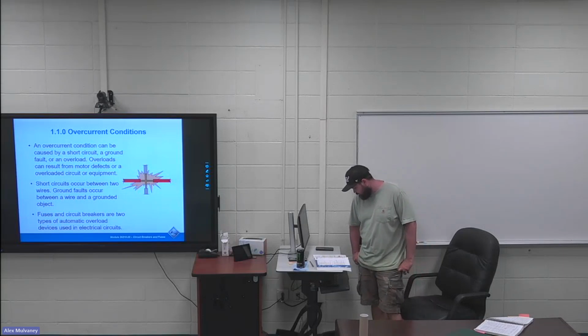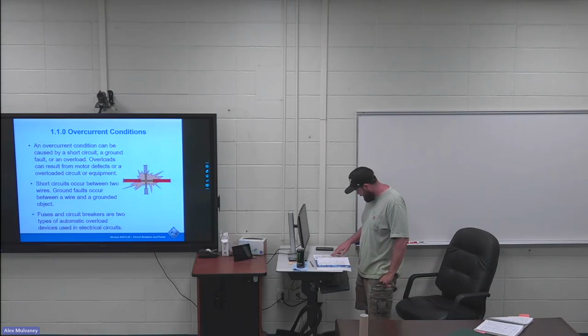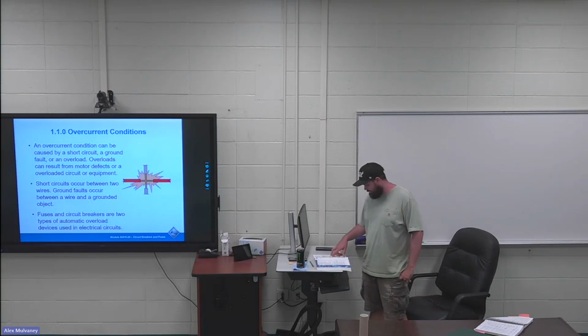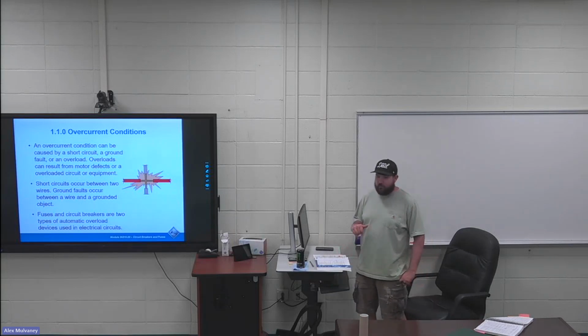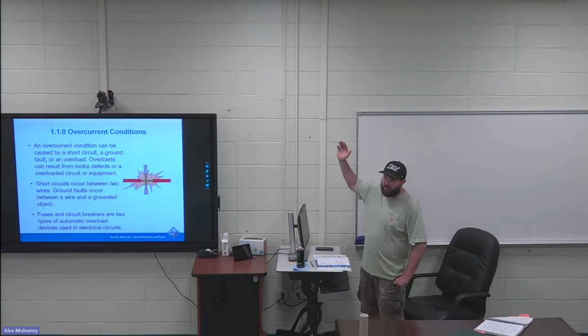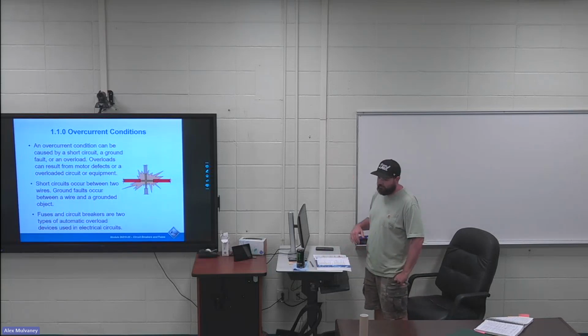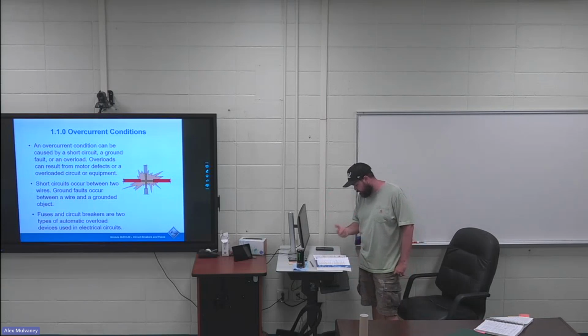Next paragraph, the first couple of sentences are another highlight. Overloads are most often between 1 and 6 times the normal current level. Usually they are caused by harmless temporary surge currents that occur when motors are started up or transformers are energized. So transformers and motors both have a high spike whenever they first start up. And once that initial spike goes away, they get to their normal running, their full load amps or full load current.